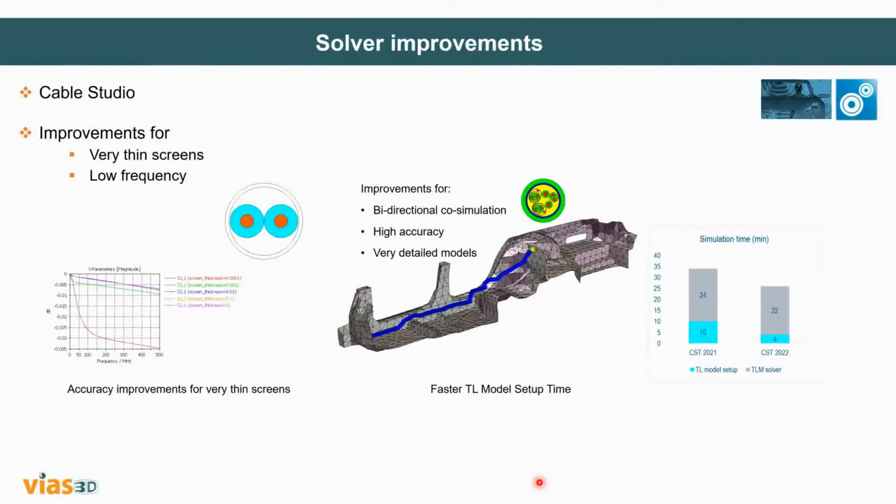So I mentioned earlier the new possibilities for simulation of cable harness at low frequency using the solver. However, whenever a complex cable cross section is required, and especially when the frequencies are higher, Cable Studio should be used, like this type of complex cable with a lot of core elements. Rather than designing directly in 3D, we should use Cable Studio at high frequency.